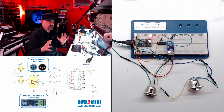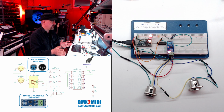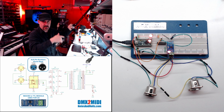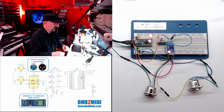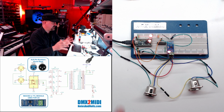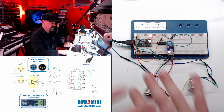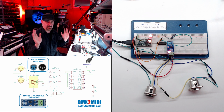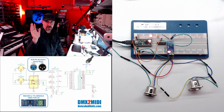So to make that signal robust, the DMX controller actually sends out 2 signals. One is the mirror opposite of the other. So if one goes up to 6 volts, the other goes to -6 volts. And then your DMX receiver kind of combines them together and makes one solid signal out of them. But none of that's going to work with our little Teensy microcontroller. It wouldn't even know what to do with it. It would just blow up.